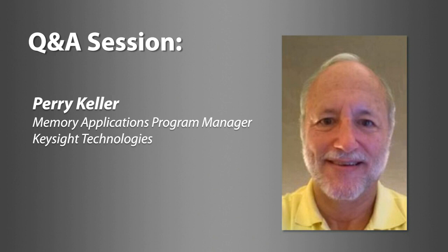Okay, here's the next question. Can you talk more about the distinctions between DDR and GDDR? Sure. GDDR has always been a generation or two faster than DDR. The reason it's been able to do that is because it lives in a world where there are much higher power and cost budgets available to it. So it's been able to assume that a lot more attention is paid to signal integrity at the system level, and so can keep the eye open at the DRAM. GDDR doesn't go through a cheap DIMM connector. The interconnect is very short, but they were the first to have to apply things like a statistical model and a receiver mask based specification to their design.